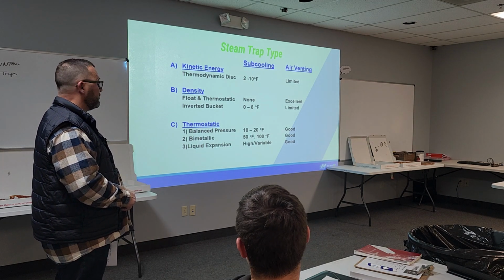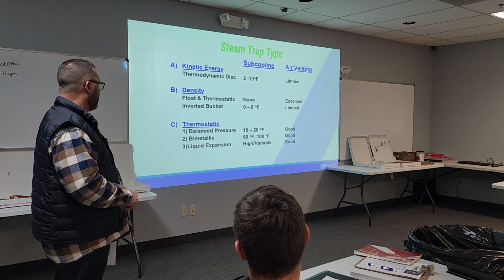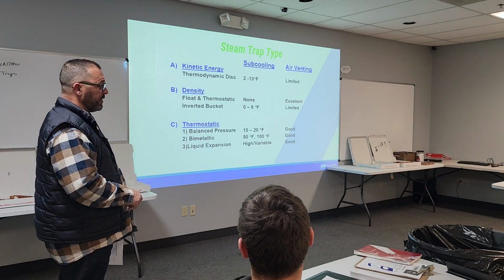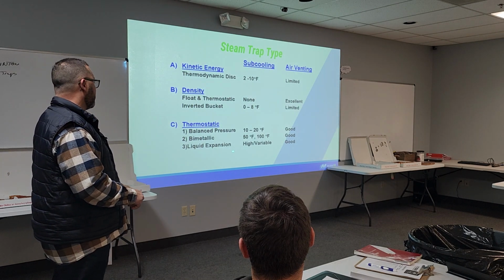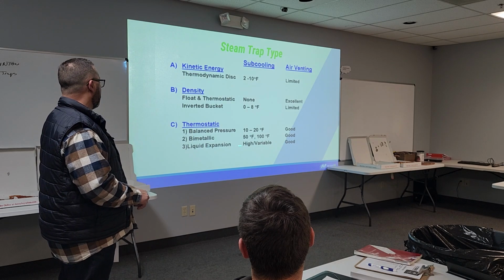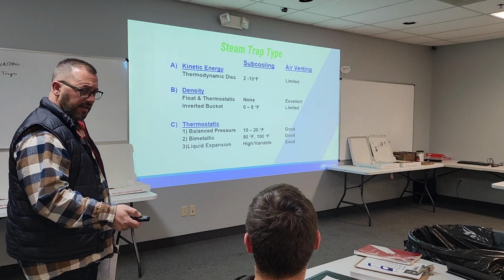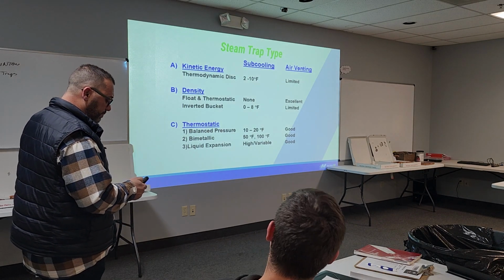We put some liquid drain. It's really a steam trap, but once the condensate gets to about 34 degrees, it dumps. So we're not going to freeze those coils. I mean, if the worst case scenario hits, we're not going to freeze those coils. That's a liquid expansion. Also can use these on eye wash stations outside, for the winter, so that the lines don't freeze and break.